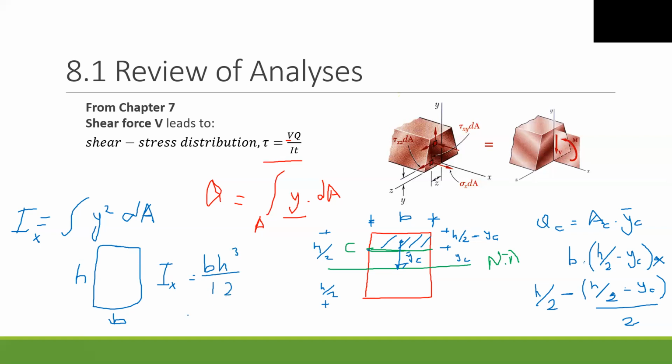It seems complicated, but it is not. You can remember these formulations from Strength of Materials 1. Just one term remaining. t is the thickness. For example, in this section, the thickness is equal to the width of the beam, which we call b for a rectangular cross section.